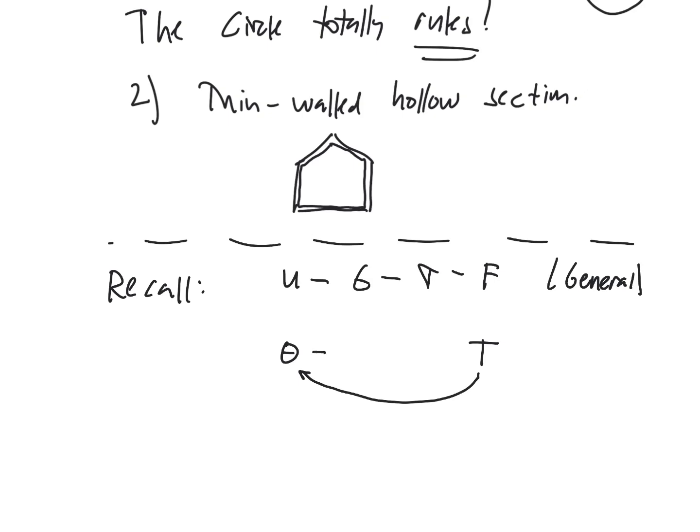Now it turns out that that twist is going to cause not a normal strain, but a shear strain. It's going to cause a gamma. That gamma then, when we link it with our constitutive law, is going to cause a shear stress, tau. And when we integrate the moment that shear stress creates about the center, that's going to generate a torque that resists the applied load.